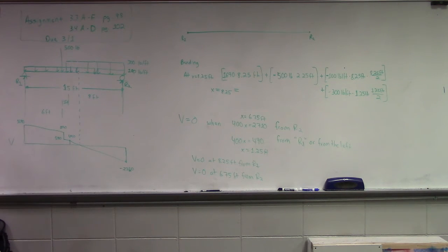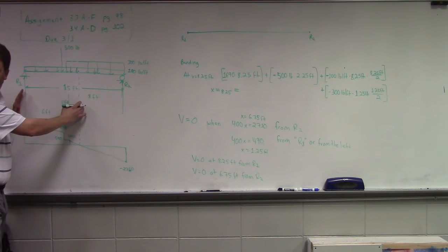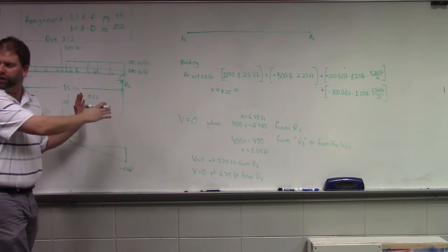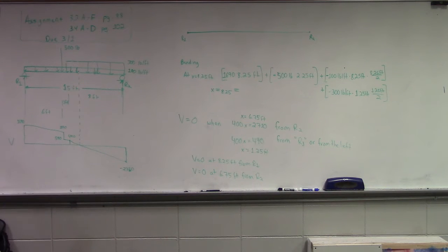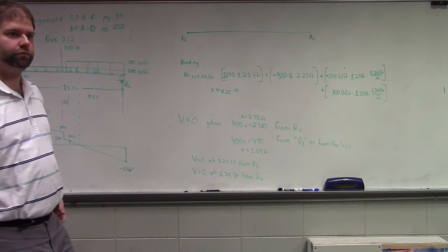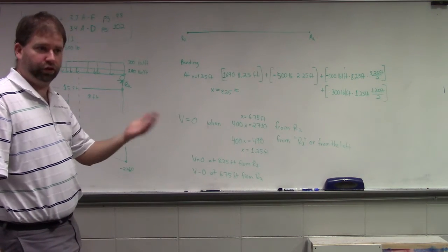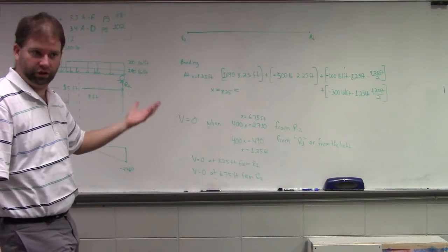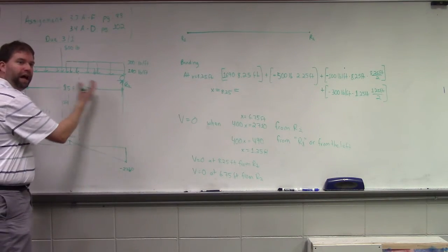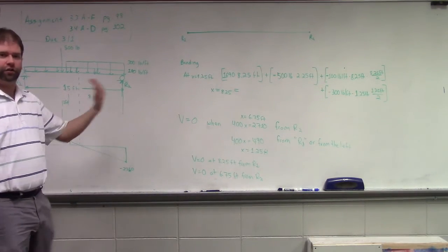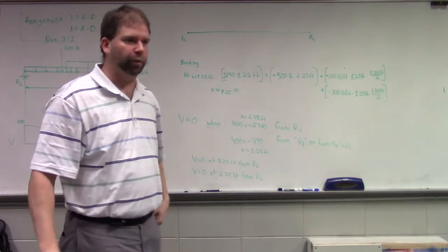So we're just looking to the left of that point, right? Yep. Okay, that clears a lot. Yeah, you don't have to consider anything to the right of that point. Just like you would do with the shear. You either march right to left or you march left to right. Do you have to go to the right of that at all? No. You'll get the same magnitude, they'll just be acting in the opposite direction, because you're going to be performing the same analysis, you're just going in different directions. So your negatives will become positives, your positives will become negatives.